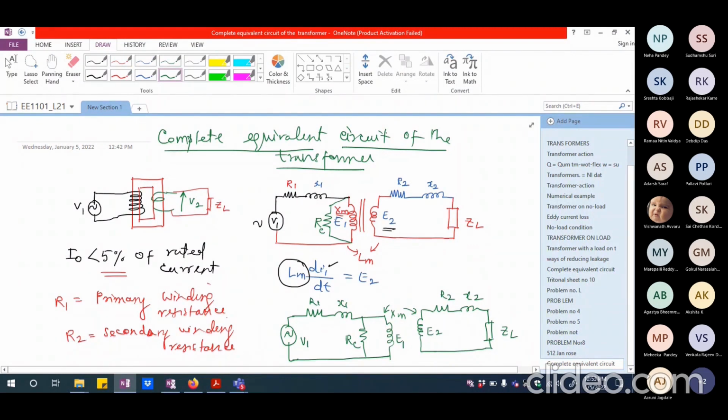Okay. So if the flux is at rated value, the flux causes the iron loss current. So the iron loss in the core. So the iron loss or core loss, okay, that is going to be essentially caused because of the voltage, not because of the current. The current does not matter. The core loss depends upon what is the voltage to frequency ratio. Voltage mainly causes the core loss.